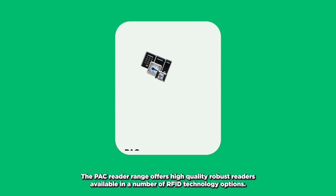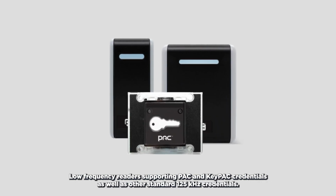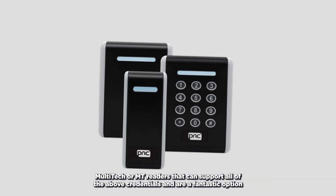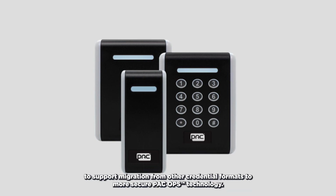The PAC reader range offers high-quality, robust readers available in a number of RFID technology options. Low-frequency readers support PAC and KeyPAC credentials as well as other standard 125 kHz credentials. High-frequency readers support PAC Ops and Ops-like credentials, as well as many other standard 13.56 MHz credentials. Multi-tech or MT readers can support all of the above credentials and are a fantastic option to support migration from other credential formats to more secure PAC Ops technology.